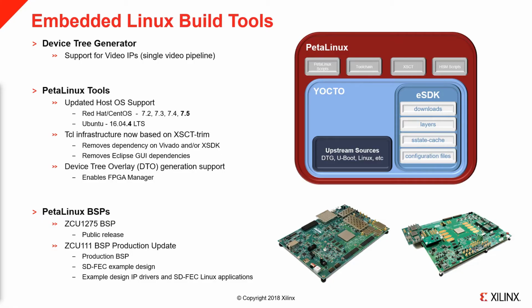To start, we've made updates to our device tree generator tool to support video IP. Specifically, the device tree generator now properly configures the device tree for strings of IP and their properties to correctly support various processing pipelines.